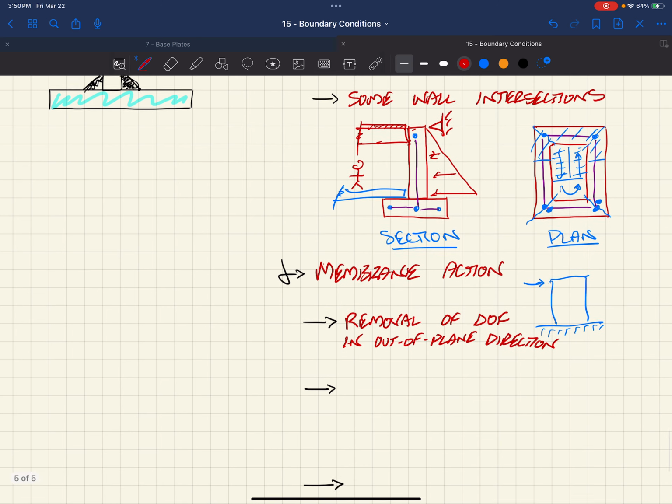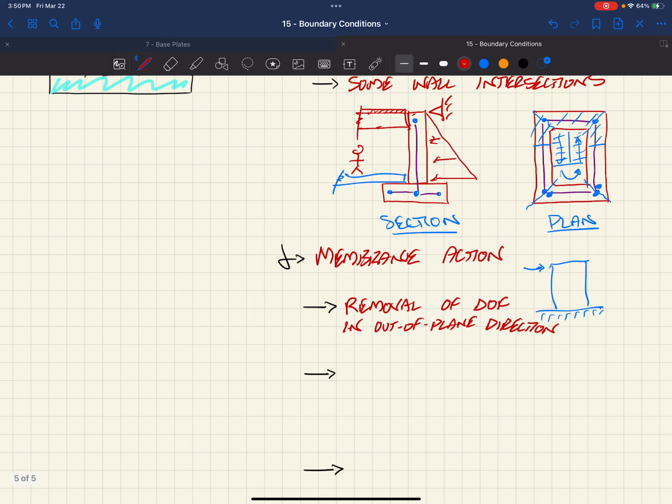Okay. So we need to be careful about doing this, because even though maybe our behavior is predominantly in plane, like the roof on the field house is a good example. It acts predominantly as a membrane, but at the same time, we have all these loads on the roof of the field house, construction live loads. If they replace the roof, we have people standing on the roof. We have live loads, snow loads, dead loads from the insulation and membrane and all of the components up on the roof, ventilation, ductwork and stuff like that.